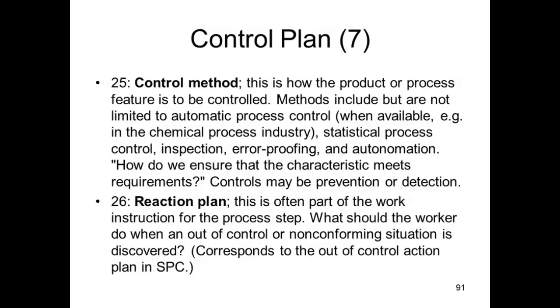The reaction plan is part of the work instruction for the process step. What should the worker do when an out of control or non-conforming situation is discovered? Okay, suppose that automation device, Shigeo Shingo mentioned the verification rods for the drilling operation. What is the worker supposed to do if the tool stops and an alarm sounds because the drill bit has broken? That would be an example of a reaction plan.